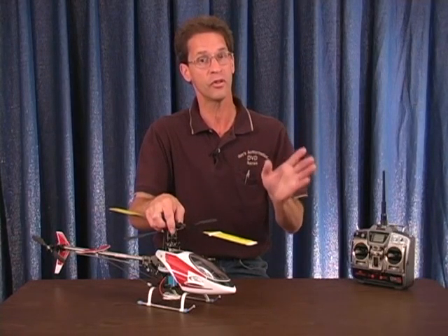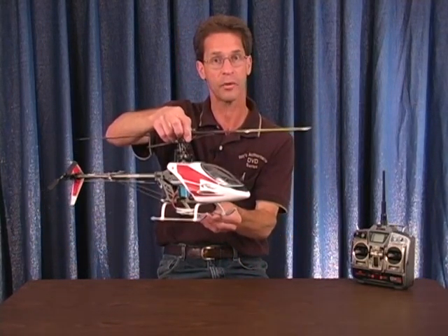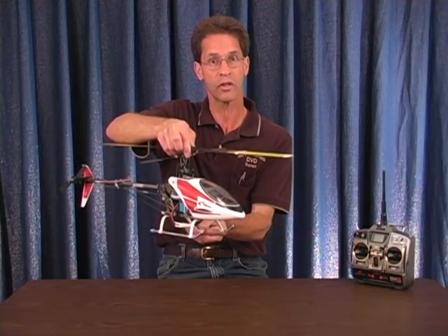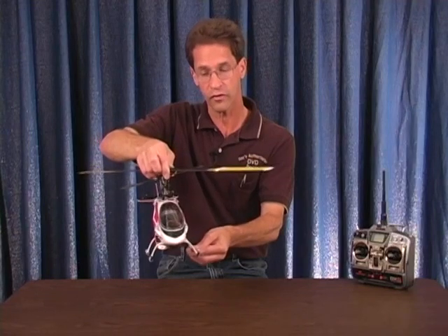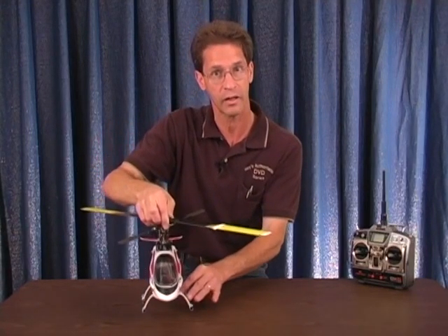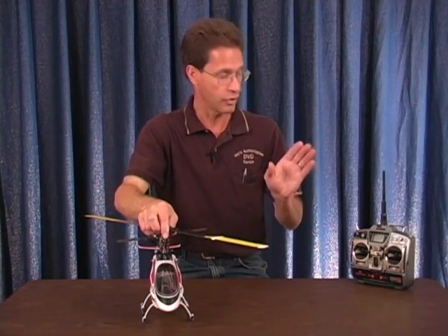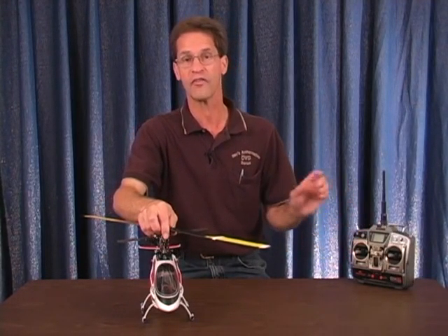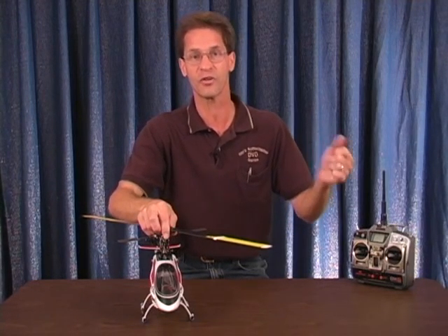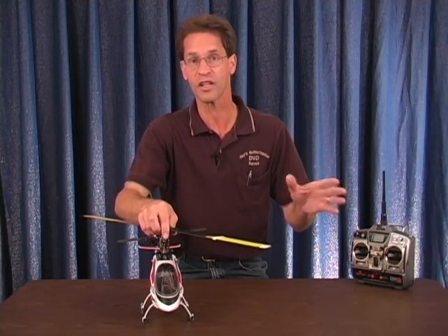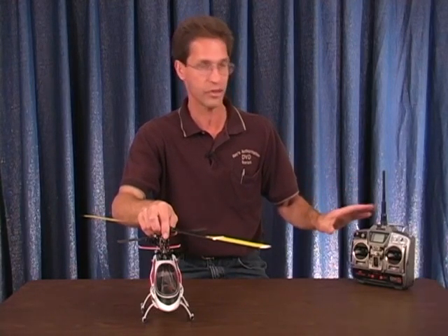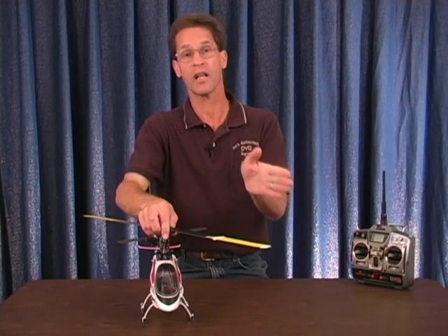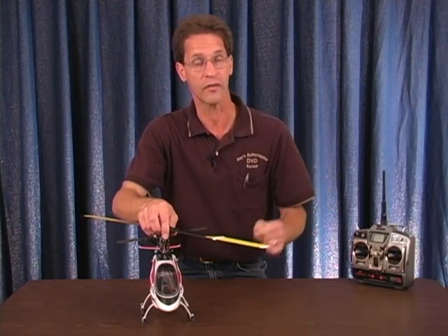So for instance, if you do a hovering auto rotation and the helicopter is at 3 feet and you flip on the throttle hold switch, the nose is going to yaw about 30 to 45 degrees to the right as the helicopter comes down. Now, you can compensate for that by giving a little bit of left tail rotor if you want to, but I find that giving left tail rotor and increasing collective pitch can get a little tricky. So normally when I do a hovering auto with the DX6, I just flip the throttle hold, add the collective pitch, and let the helicopter yaw to the right 30 or 45 degrees.